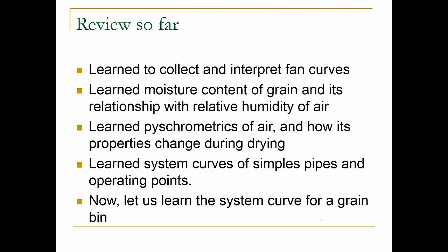Before we get started, let's stop back and think about what we have done so far. We spent quite a bit of time last week learning how to collect a fan curve. We went to the lab, understood how the fan is connected to a long pipe. We used a pitot tube to measure the static, total and velocity pressures and plotted a fan curve. We also learned to interpret the fan curve. Where are the stable and unstable regions in the fan curve? And we looked at fan loss, how does it change? And we also looked at multiple fans. How does the fan performance curve change?